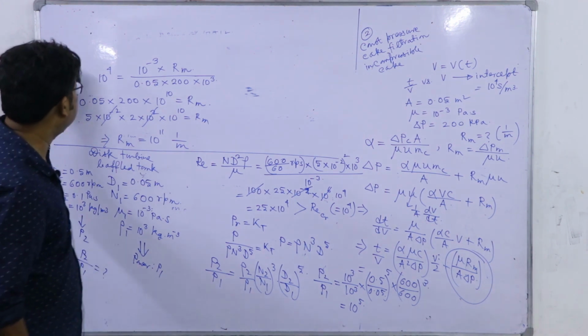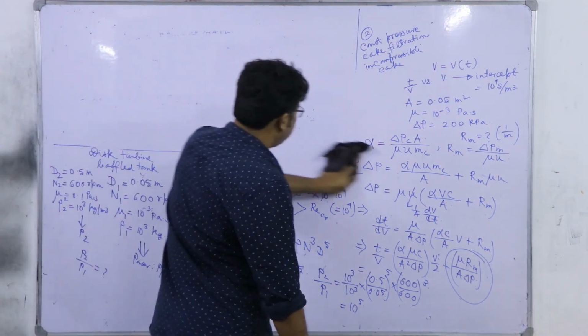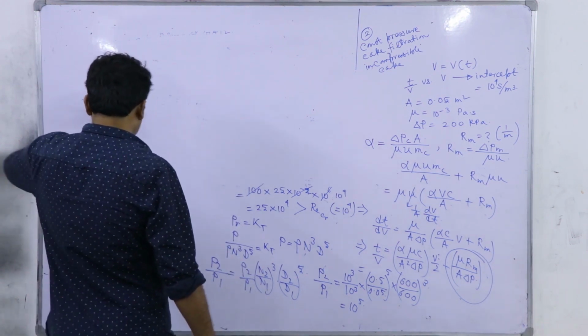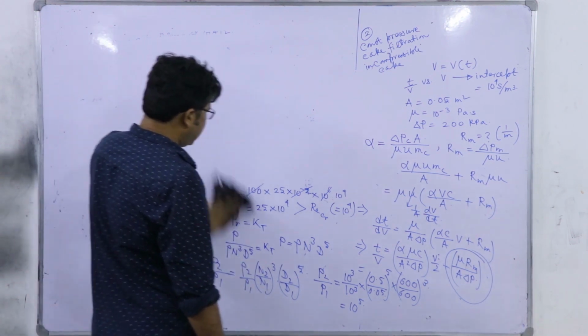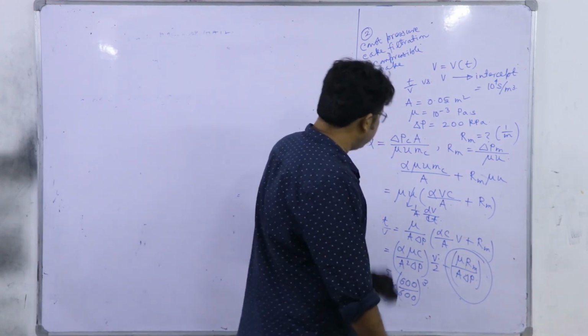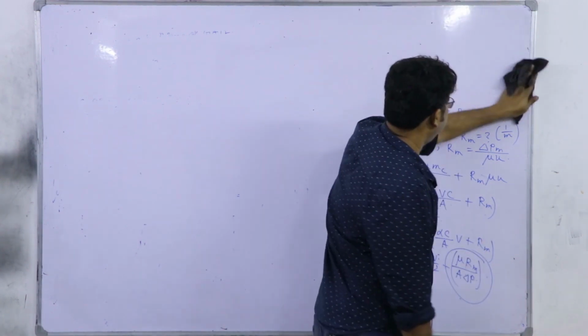So, the equation and the scale up relation will be entirely different. So, that we have to note in dealing with that. So, basically if the lab scale data or the pilot plant data is available, you must calculate the Reynolds number and confirm the regime of this flow.